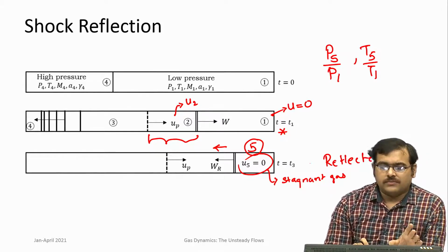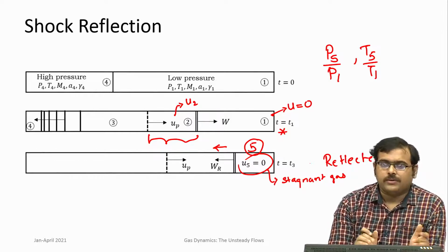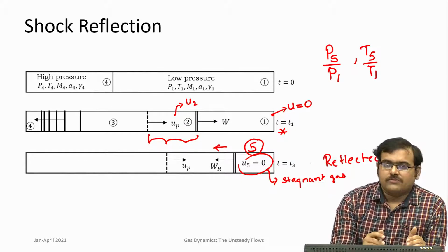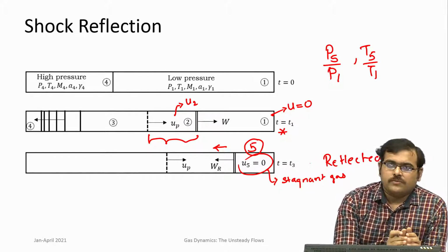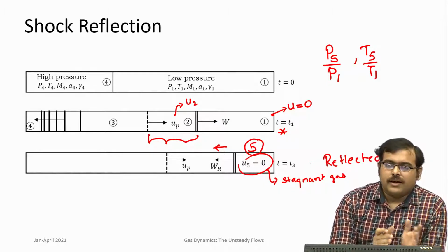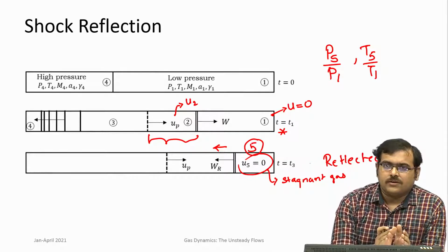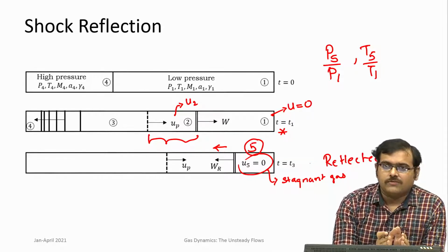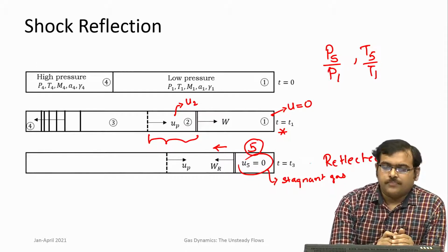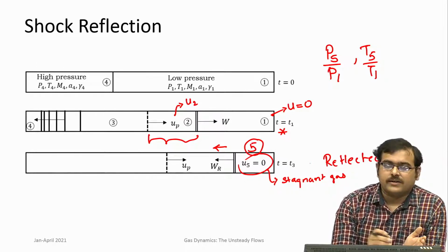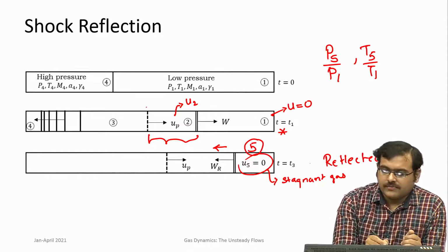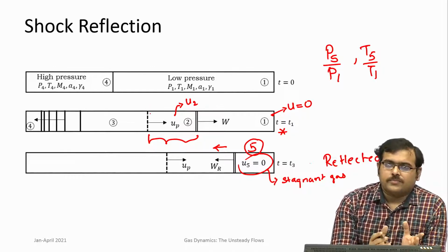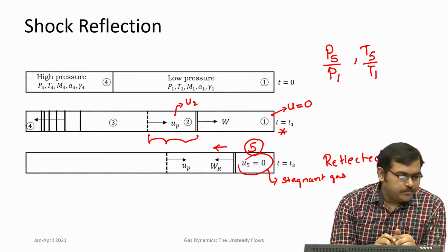and the consequence of that is a wave structure is set up in the shock tube consisting of a shock wave that goes into the driven section and expansion waves that move into the driver section, and the surface or the sort of virtual boundary that separates both the driver and the driven sides is the contact discontinuity or contact surface, and across the contact surface pressures and velocities are the same.